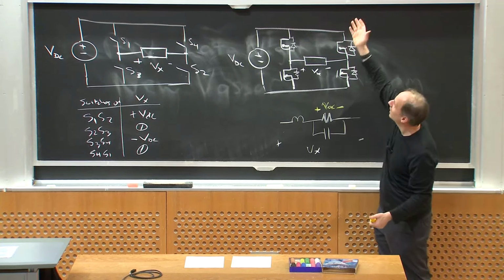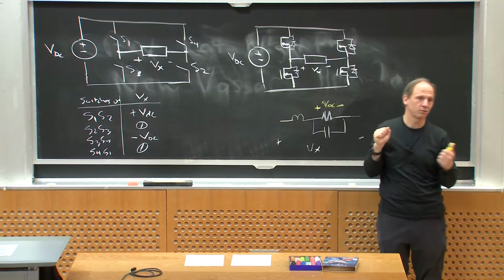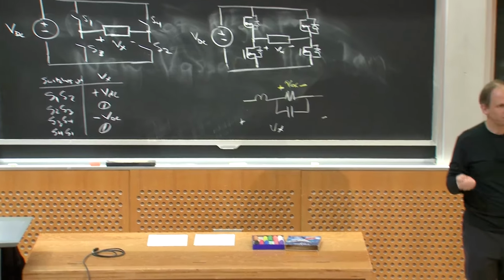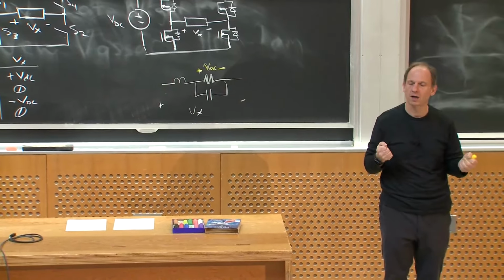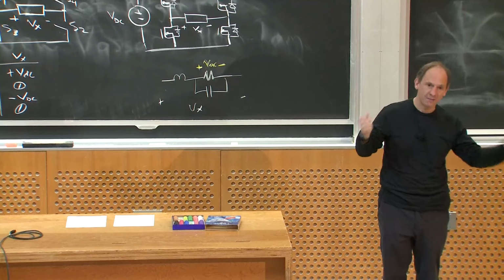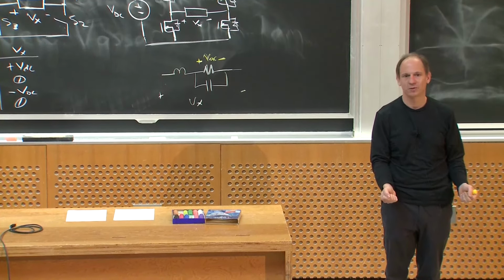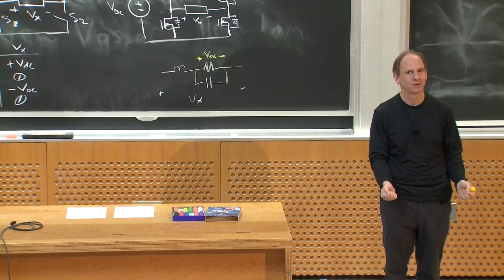Well, by making it half-wave symmetric, I don't need to kill 2 omega t, I just need to kill 3 omega t. All right? So there's a large motivation to control the harmonic content of your waveforms by picking waveform symmetries, and hence the interest in half-wave symmetric waveforms. Questions?